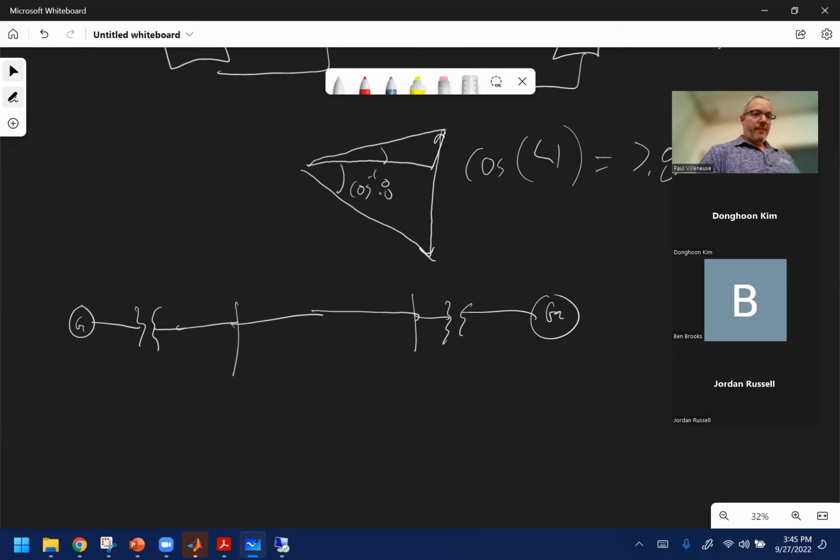Here's G1, G2, T1, T2. So this, you should have known, was configured this way, and this transformer was configured that way. It steps it up to the transmission line voltage level to reduce line losses, and then steps it down. Some of you said these were reversed, going from 200 kV on the generator winding and stepping it down to 20 kV. So your V-base values were a little off.